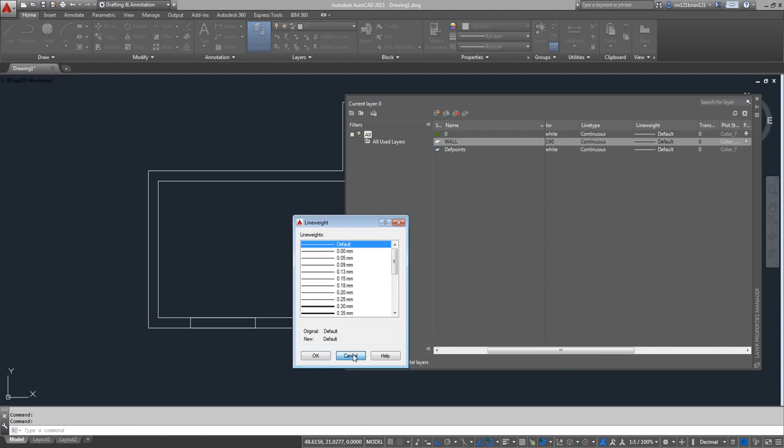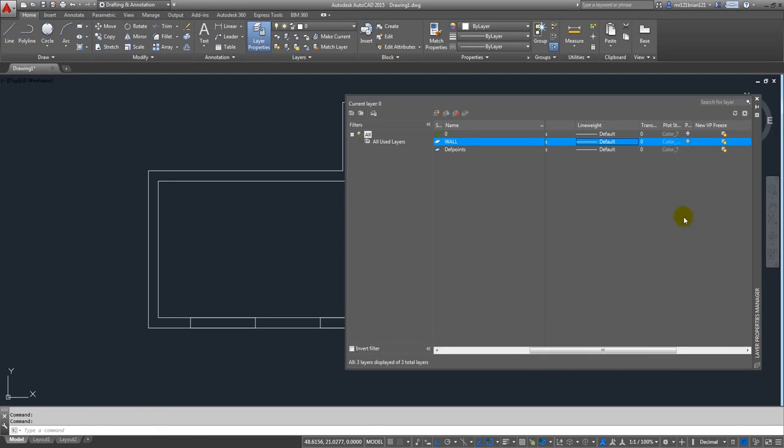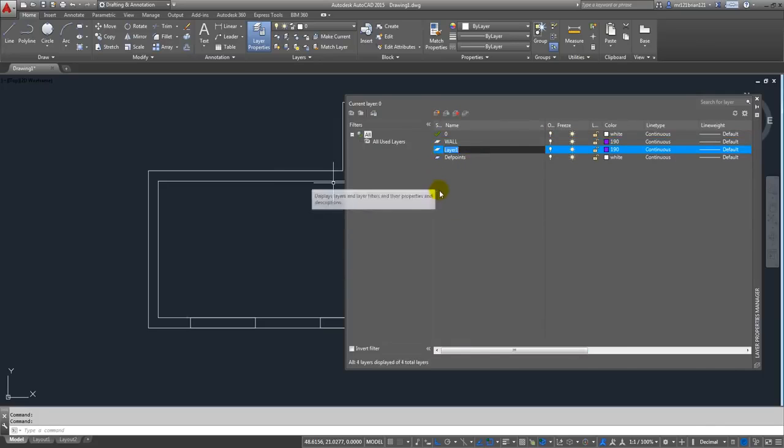In this case, I'm going to leave all at default, and if it's going to be printed or not. Then we are also going to make layers. You can make all the layers right now, or you can make them when you are drawing. For example, equipment, units, or text or annotations, and etc. whatever you want.